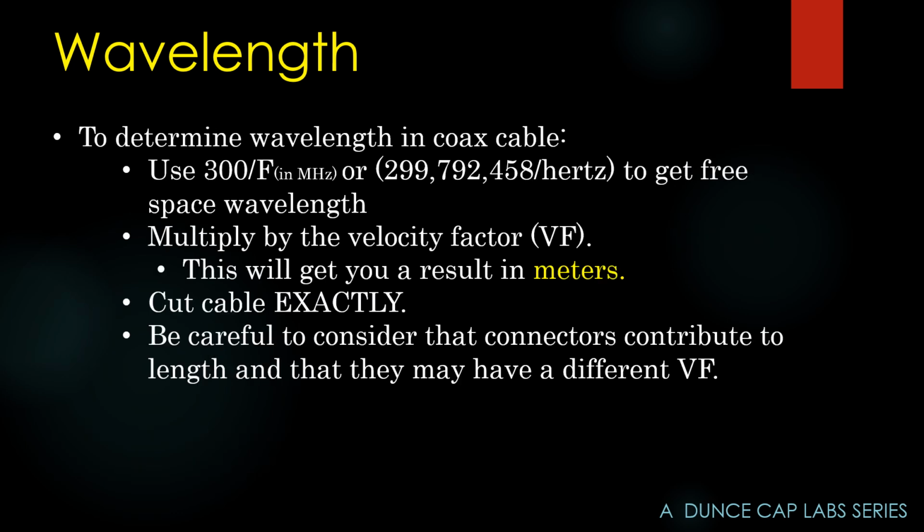To determine the wavelength in coax cable is actually very easy. I use 300 over F in megahertz. I then multiply that result by the velocity factor. This gives me a length in meters. If I cut the cable exactly, I'm good to go.